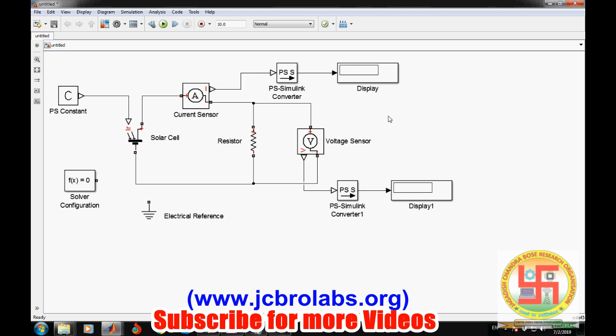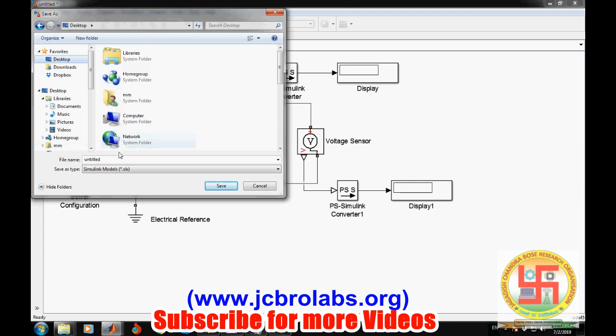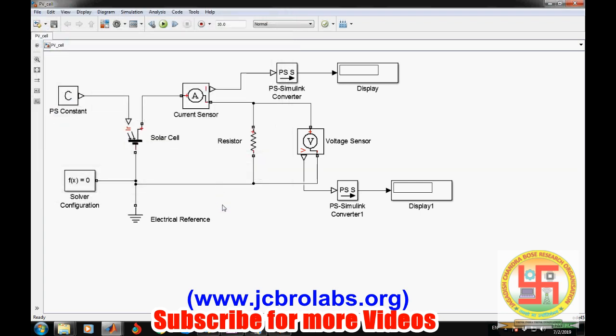Yeah, that's fine. Now we need to connect the solver configuration as well, and the reference circuit, electrical reference. So that's it. Now let's save it. Let's save it on desktop. Make a PV cell simulation. Okay, let's save it.